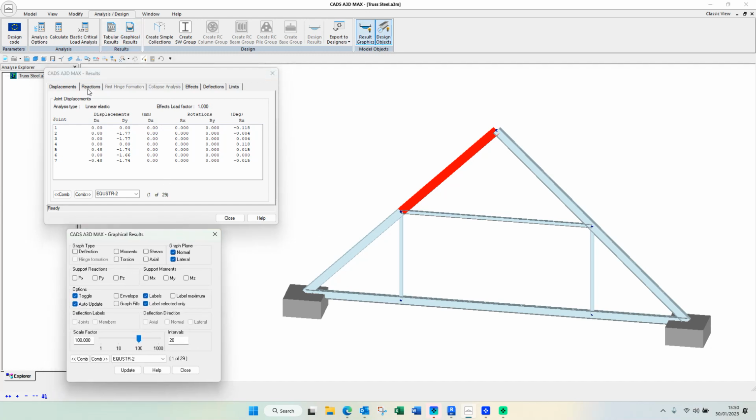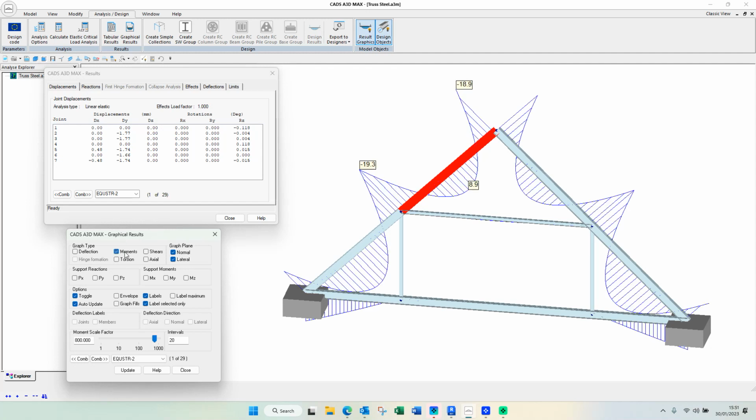So we can choose to have a look at the bending moments. I briefly showed you something like this before. You can see I'm choosing member 5. If you don't want to choose that particular member, you can label everything up. Indeed, the program even gives you a chance to see what the maximum values are for the whole frame.